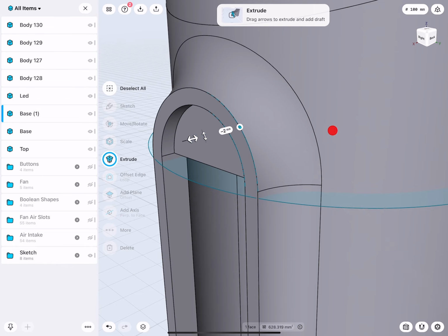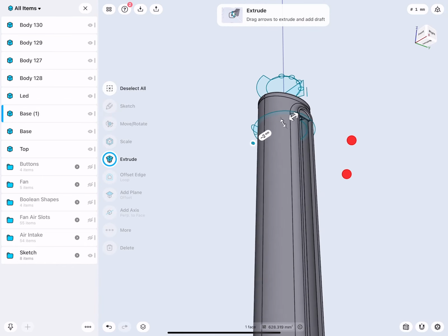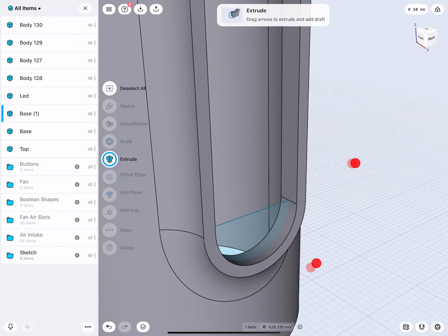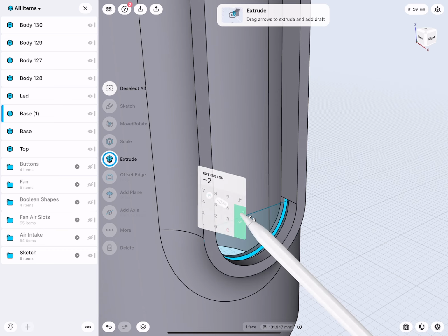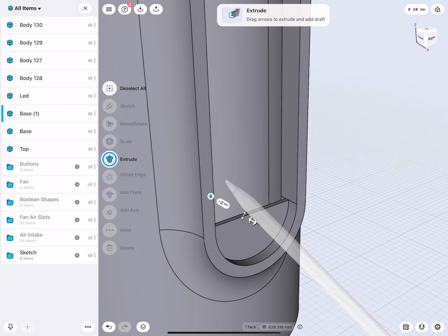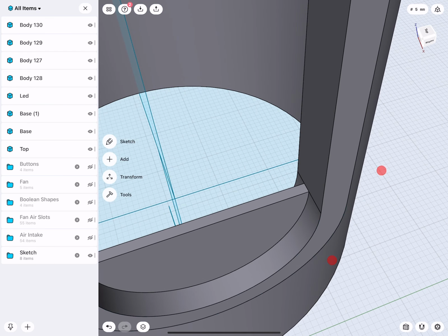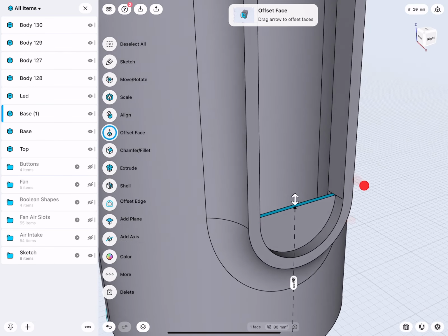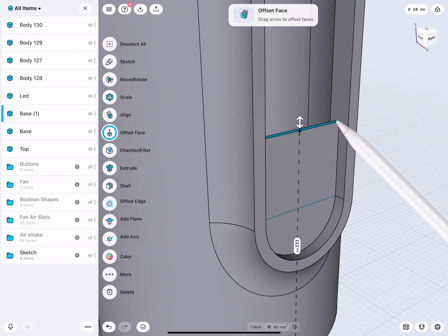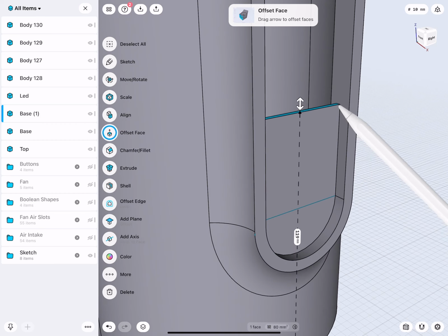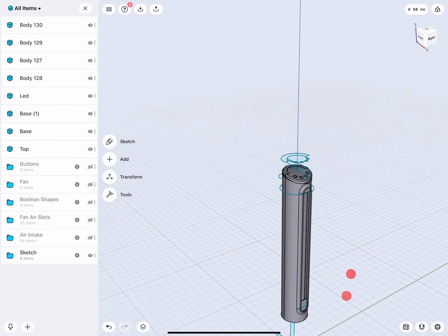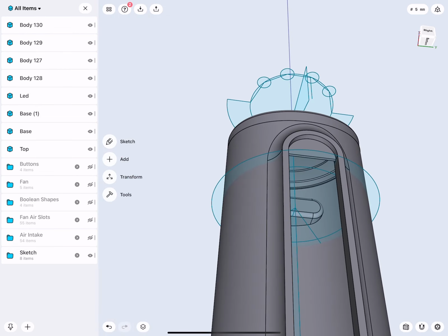join union, simply extrude a cap that fits in there. And I can do the same down here. 2 and union. If this is not big enough, I can even select this face and move this one up. Very nice. You see, this is all fairly simple.